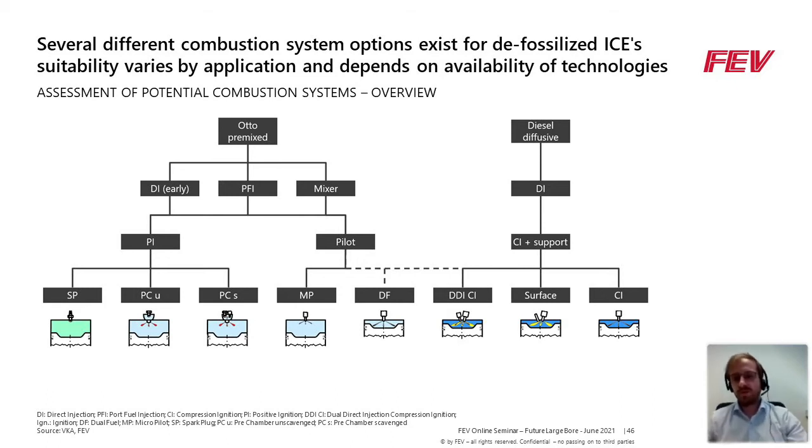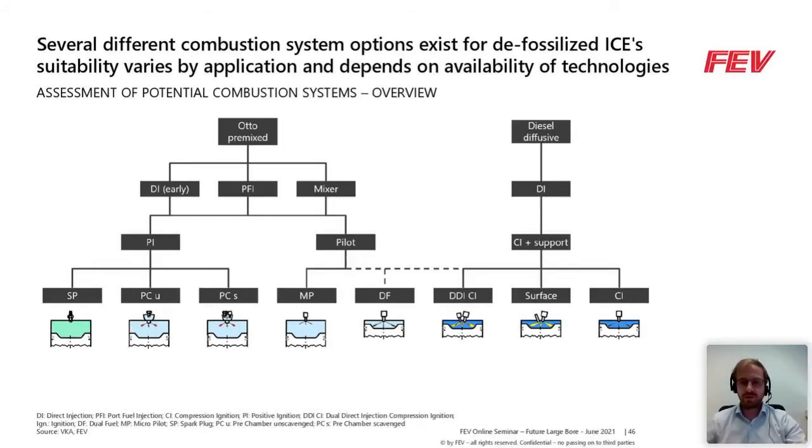I'll be focusing more on the thermodynamics or combustion system related part of the high-speed webinar, and we are starting the presentation here with a matrix of possible combustion systems. We can see the matrix is divided into the premix concepts on the left side and the diffusive ones on the right side. Starting with the premix ones, we have different ways of introducing the fuel.